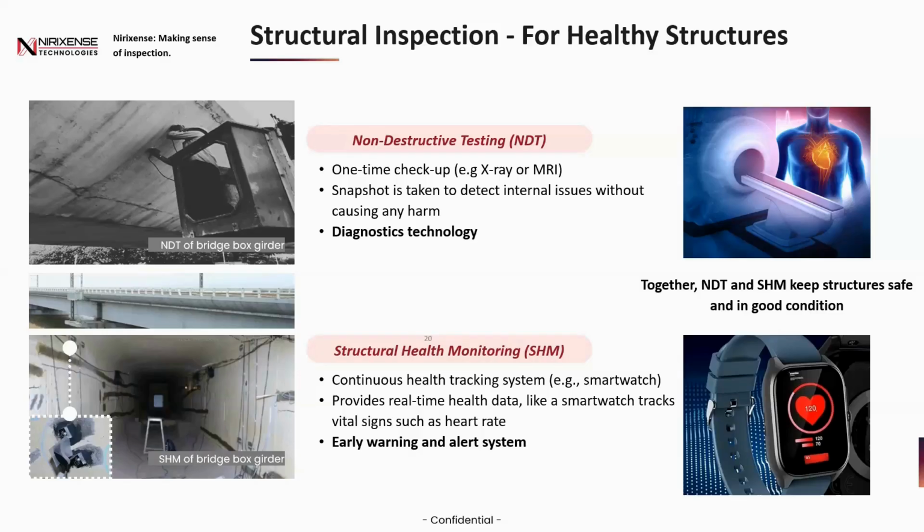Structural health monitoring is like wearing a smartwatch. You are not wearing it to check every day if you're developing some condition, but over time it has collected a lot of information, so it can start telling you trends that are appearing over time. So it may say your blood pressure seems to be increasing in the last 1 year, so maybe there is a problem. You cannot diagnose something from this, but then you can go and do non-destructive testing. Right. So then you can go do a check and find out what the problem was, because I'm starting to see something abnormal. Right. So both are needed.